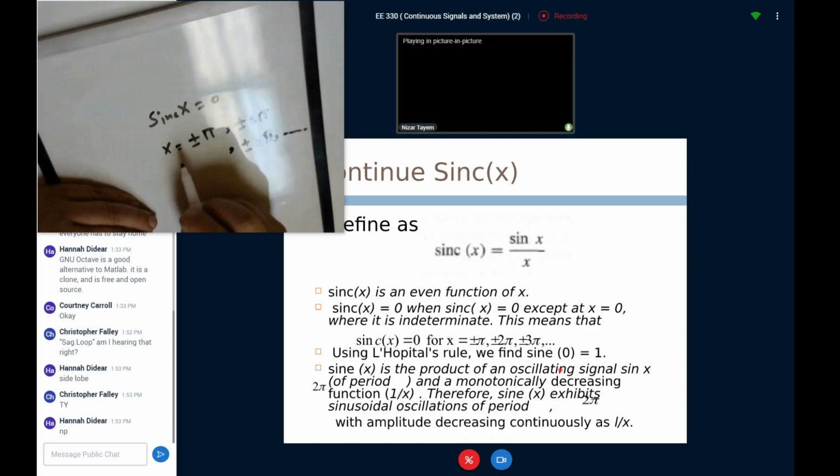So this is the angle here, right? 3 omega over 7. We're going to get the first zero crossing at plus or minus pi. Right? This is the first zero crossing. The second zero crossing will be when 3 omega over 7 is equal to plus or minus 2 pi. Okay? So for the first zero crossing, we can find omega from this equation. So omega will be equal to plus or minus 7 pi over 3. So this is the first zero crossing.